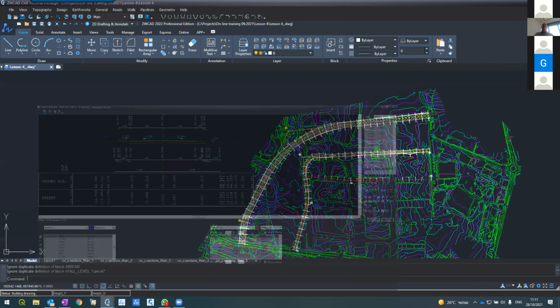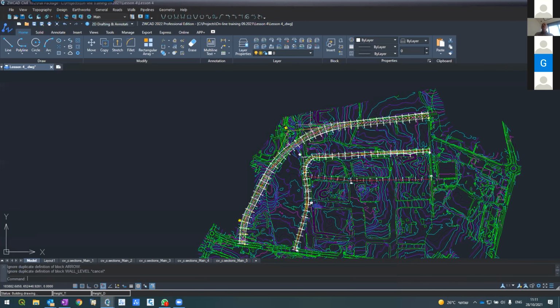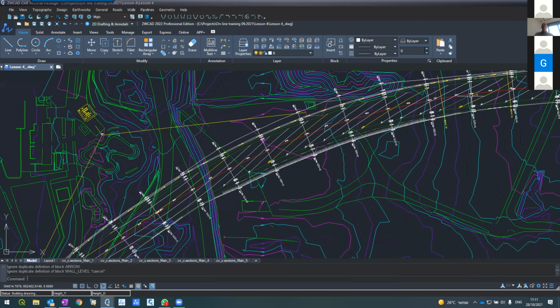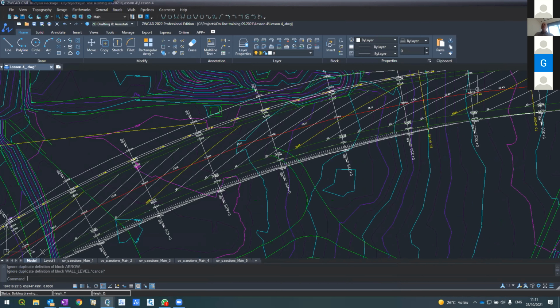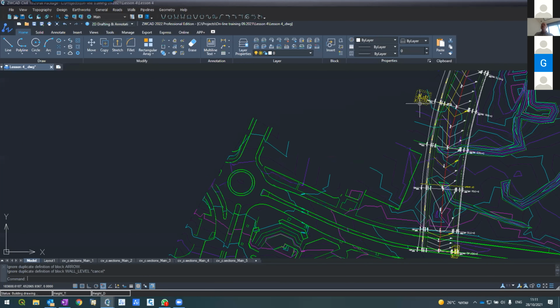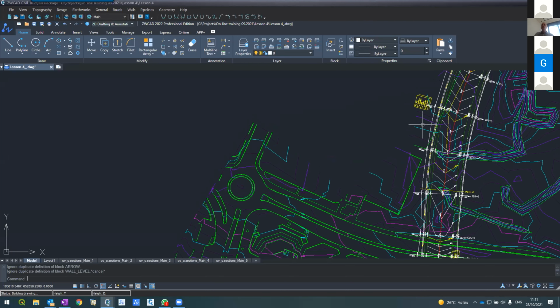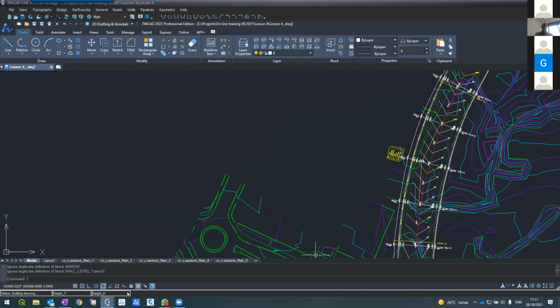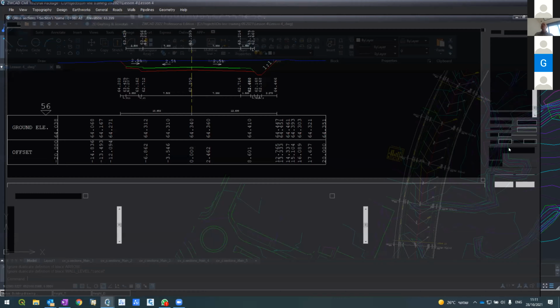First of all, now it's 40 meters here and not 30. So the super elevation should change as well. And now there's a new curve here, which you can see from the contours, there's no super elevation at all. We didn't design it. So I'll press the super elevation again.